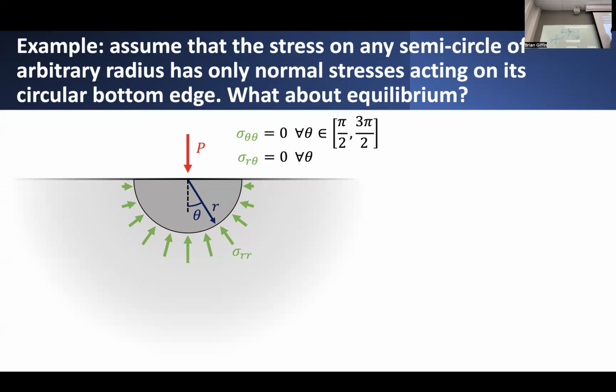But we can still represent that in terms of sigma theta theta, which is basically the normal component of stress anywhere on this top surface, as well as sigma theta r, the shear component of stress, which have to be 0 all along that top face. All right, something else that's useful to think about is we could consider not necessarily taking equilibrium on this infinite plate.